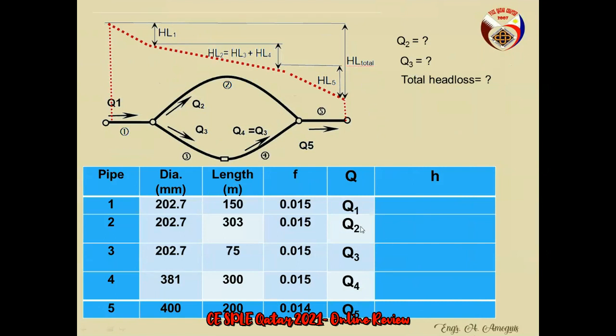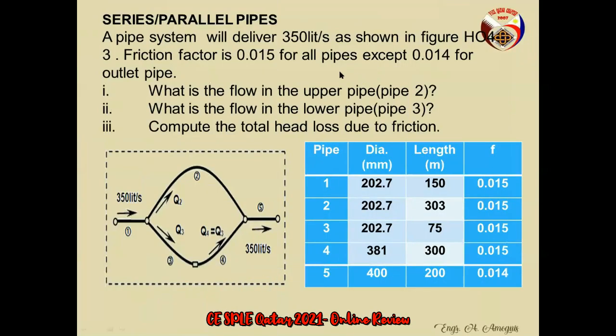So, ganito. Since ang binigay sa problem is friction factor, may sinasabi ba dito na use Mannings? Use Darcy? Use Hazen-Williams? Wala, di ba? For exam, friction factor, that is for Darcy. Pag roughness coefficient or roughness constant, normally that is Mannings. Ayan yung mga common. Kasi may mga board exam talaga na hindi klaro, so of course, automatic na gawin mo na ganun.